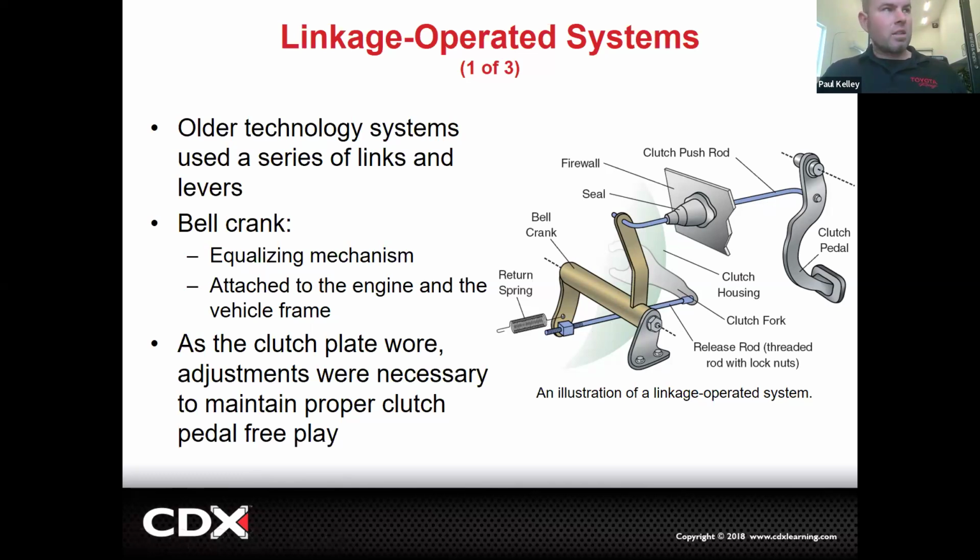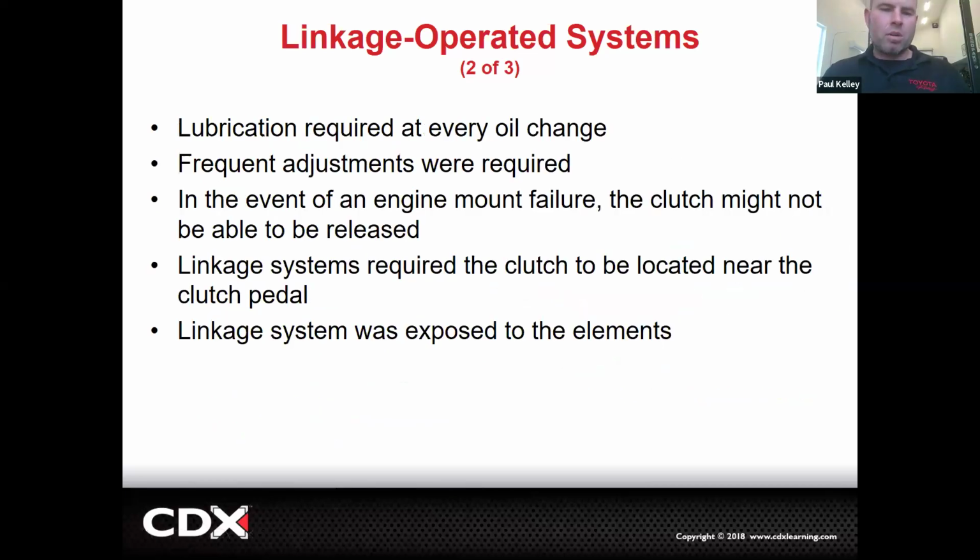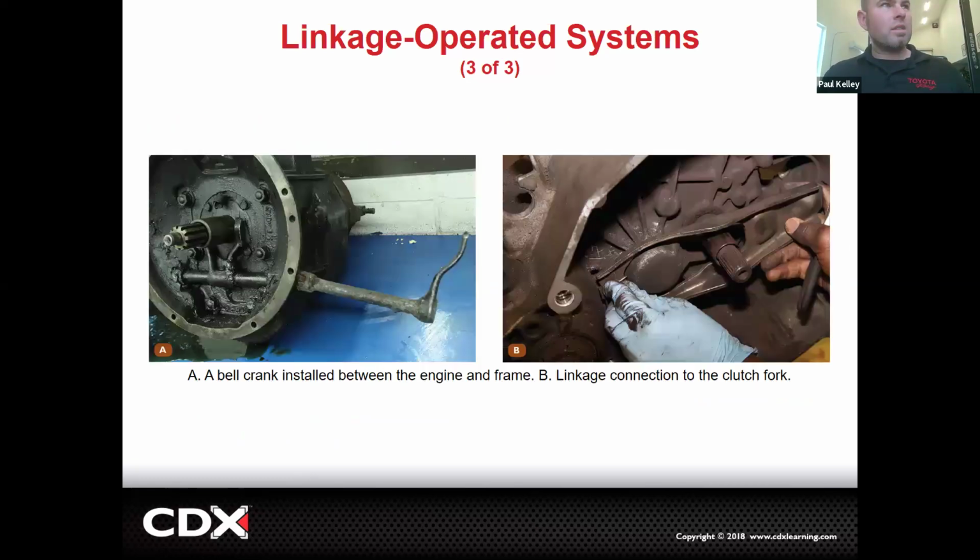But again, as the clutch plate would wear, you generally have to loosen up that push rod to account for it. Kind of similar to a cable. All right, but not real common. It just needed a lot of lubrication. So like, this is the design. You'd have to lubricate these different various things. But back in the day, remember, we did LOF, lube oil filter.